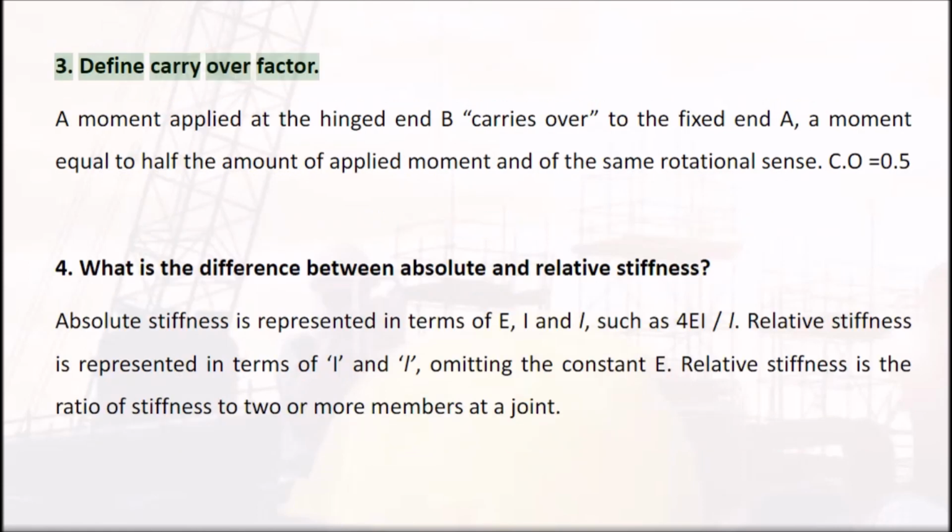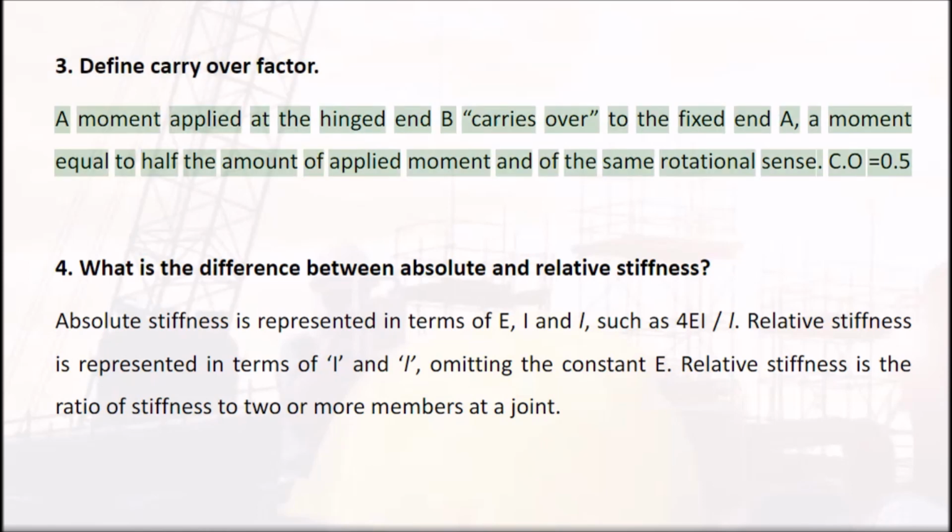3. Define carryover factor. A moment applied at the hinged end B carries over to the fixed end A, a moment equal to half the amount of the applied moment and of the same rotational sense. C.O. equals 0.5.